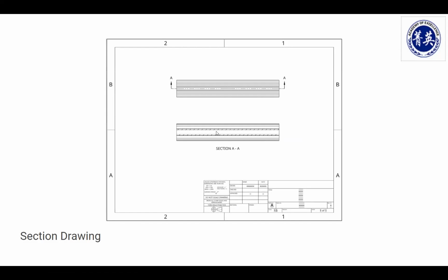To show what it looks like on the inside, we talked a little briefly about a section drawing, right? So A points that way. What that means is it sliced this model in half and is looking in that A direction. So section AA shows what that looks like. The little diagonal lines that go down the chain there mean it's solid. So you have a solid side and the core hole right there and some other side over there.